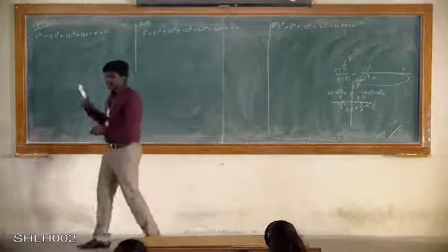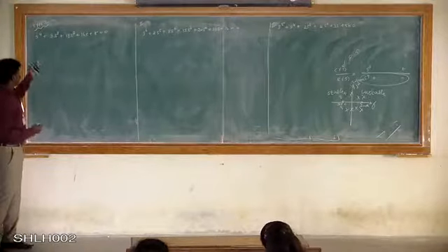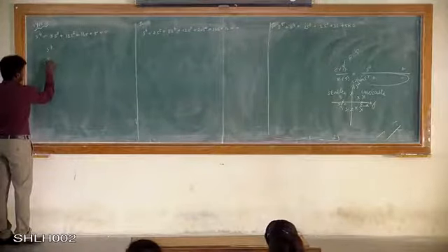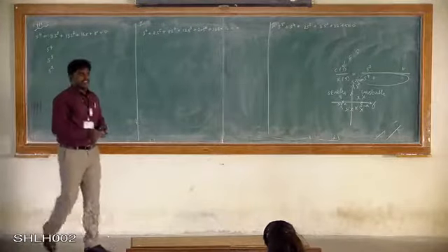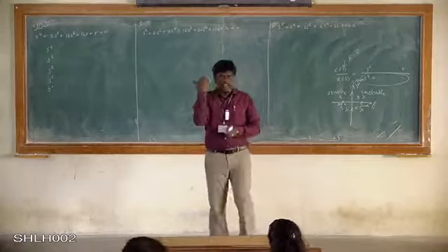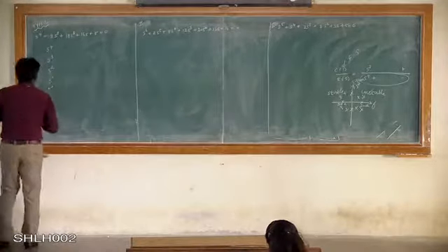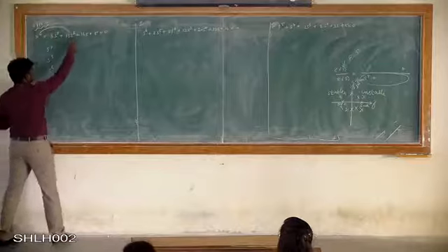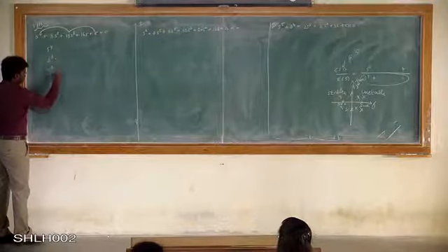So using the Routh table, we will have to say whether the system is stable or not. Okay. So it is a fourth order system. So write it like S power 4, S3, S squared, S1 and S0. Since it is a fourth order system, we write from S power 4, S power 3, S squared, S power 1 and S0, that is the constant value, right? So when you make this table, first write S power 4, then S squared, then the constant value here. Okay, so write only the coefficients of all this.